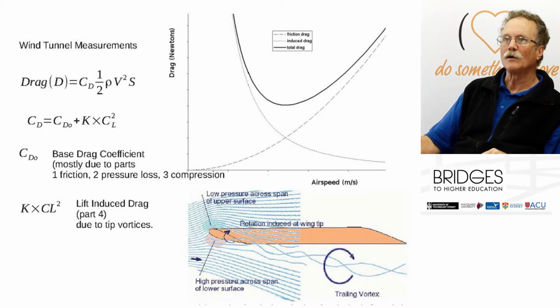When we look at the equations, we can see that we can produce a drag, which will be our constants, half, CD, drag coefficient, rho v squared S, as we had for the lift. Whereas in this case, because of these complexities, our drag coefficient will be made of two parts.